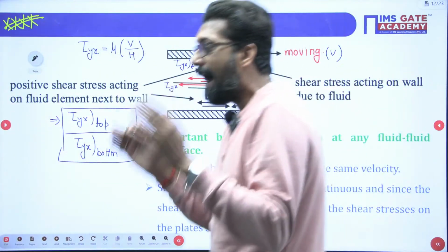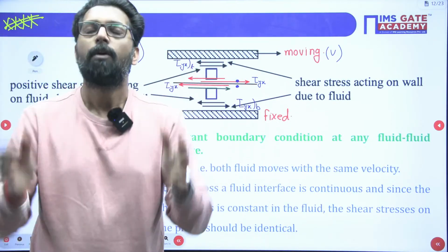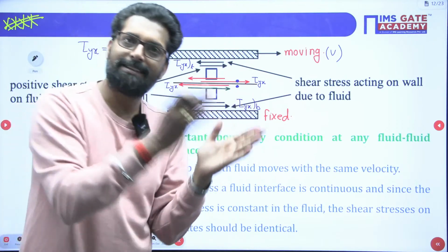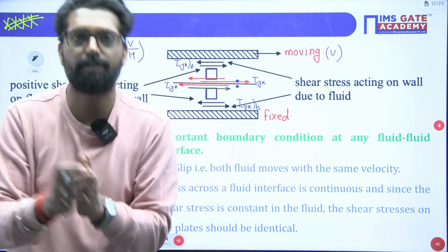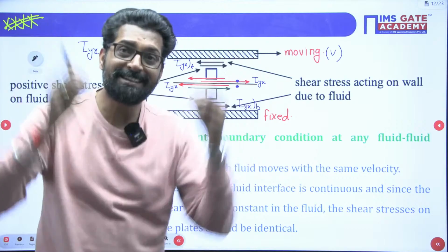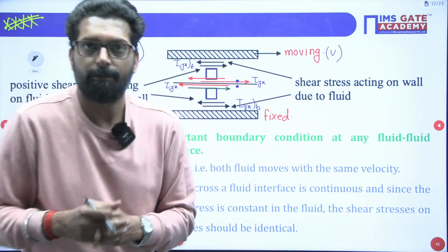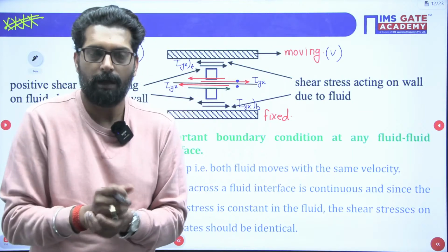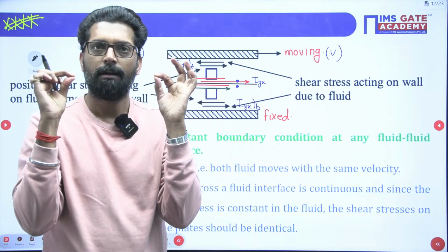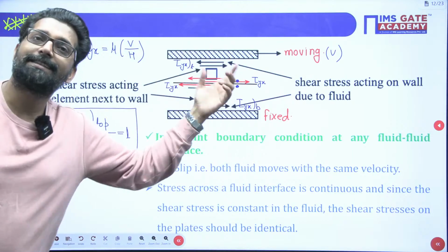So while the fluid is flowing, you cannot just say that shear stress is 0, constant, or varying. You have to understand under which mechanism the flow is induced: boundary displacement, pressure difference, or a combination of these two. Accordingly you can decide what the shear stress is.